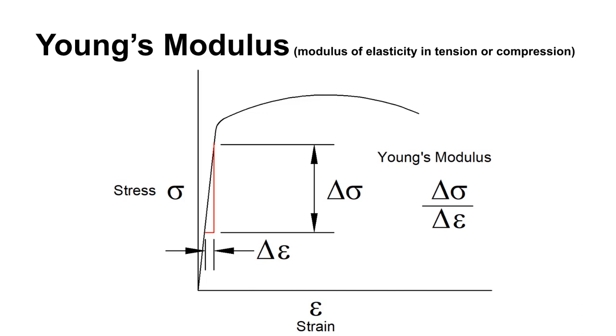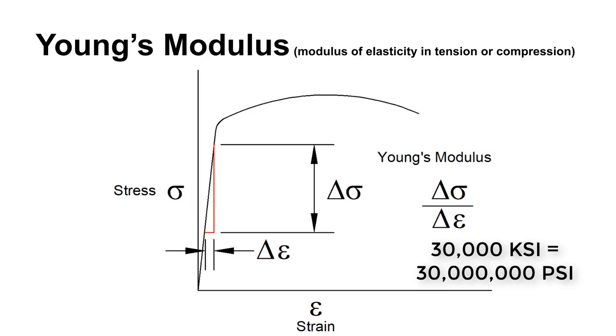Now, when you're doing the math, sometimes it's convenient to get everything into the same unit and then worry about whether it's giga or mega or kilo or whatever when you're done with all of the calculations. Same with the inch values. If we had KSI units, a typical Young's modulus measurement for steel might be something like 30,000 KSI or 30 million PSI.